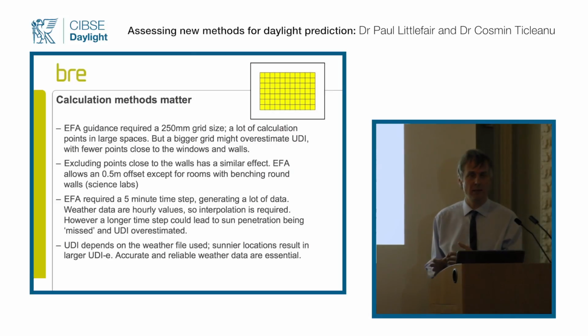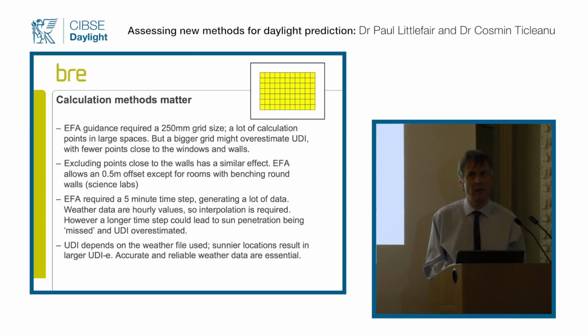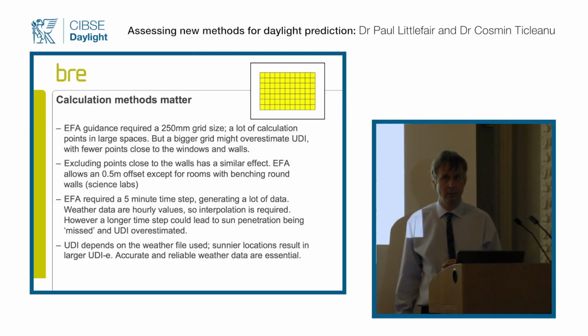And overcast days tend to be not so bright, and really it's the skies in the middle that tend to be brighter, just purely in diffuse daylight terms. So the diffuse daylight doesn't actually vary so much according to climate, whereas the sunlight does. And of course the sunlight doesn't really affect the daylight autonomy, but it does affect useful daylight illuminance.